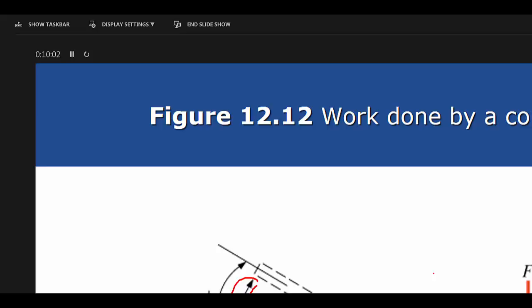And there again, typically with RPM, let's go back to that tractor. On a tractor, everything is typically rated at either 540 or 1,000 revolutions per minute, depending on what your tractor and implement are. That's just like this 300; that's what it's set up to do. Now, you can go faster or slower than that, so there has to be some kind of safety factor built in.